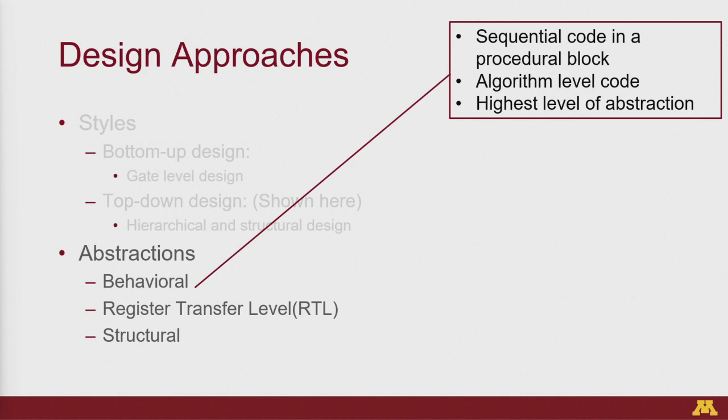For example, if you're implementing an adder, you would literally write code along the lines of A plus B, right? You do not go into the details of how an adder is implemented, or what the connections and sub-blocks are, but rather you leave it at an algorithmic level and let the tool interpret it and design it for you.